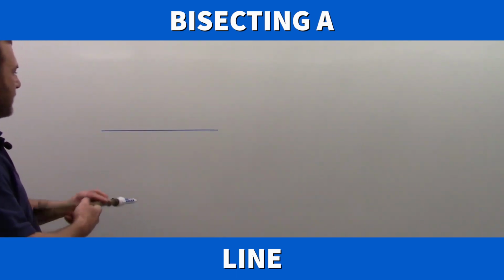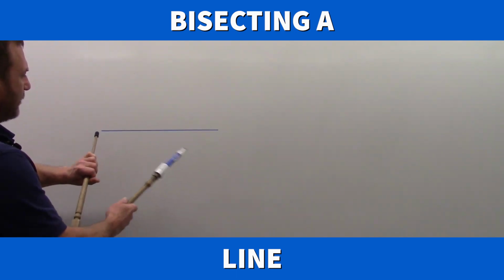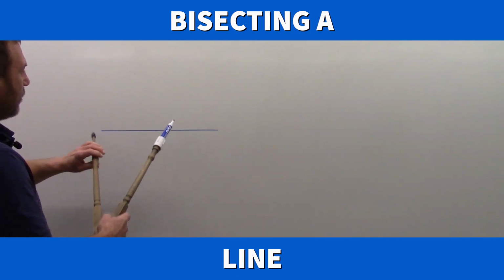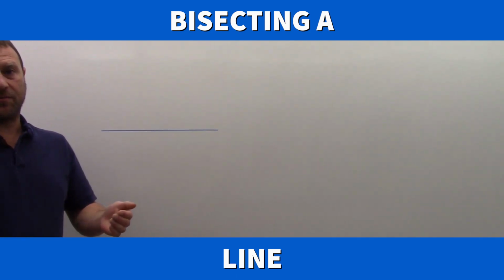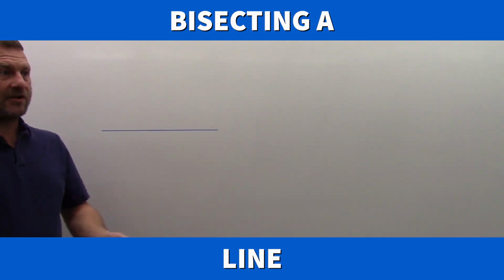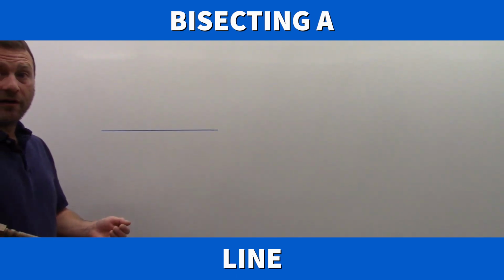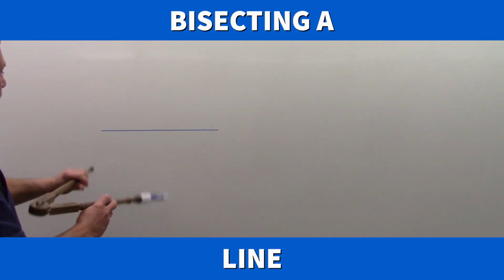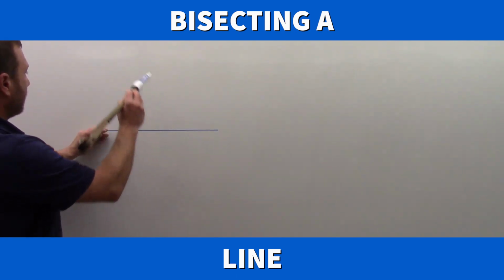So what we want to do is set our dividers to approximately 3/4 the length of the line. Now, you'll see as we go that the 3/4 is a ballpark. It's approximately 3/4. It doesn't need to be exact. What we want to make sure of is it's beyond halfway. And the further past half we go, the more accurate, because the further away our points are going to become. So I set to approximately 3/4 and I swing an arc from one side.